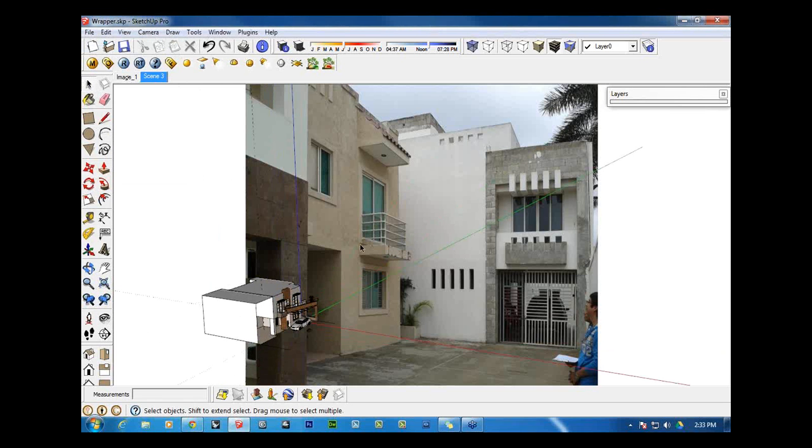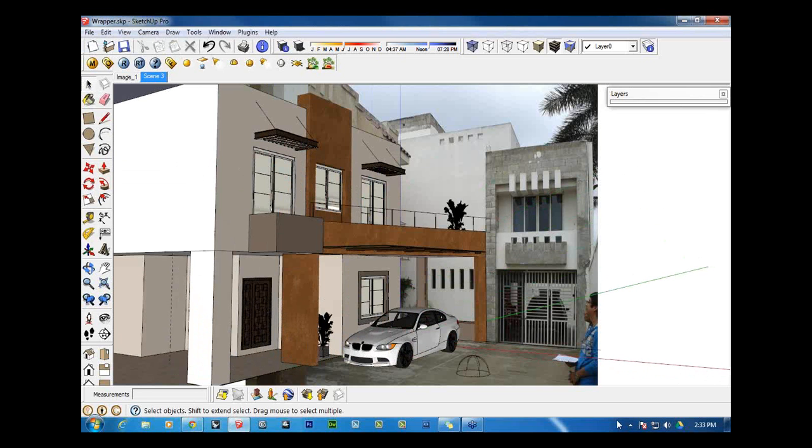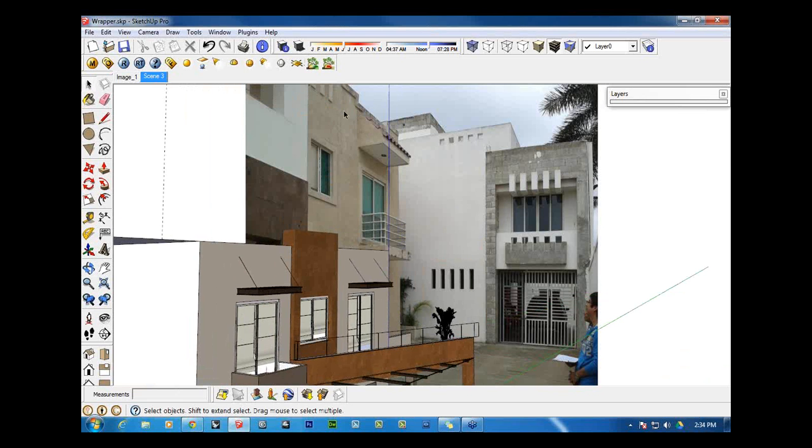Also, you will be able to see the image if you use photo match, but for some reason, we don't fully support the photo match camera, so we have to tweak the scene a little bit to create a different camera very close. You can see that I intentionally changed the camera for this scene, so I'm not matching perfectly the distortion in the left building.